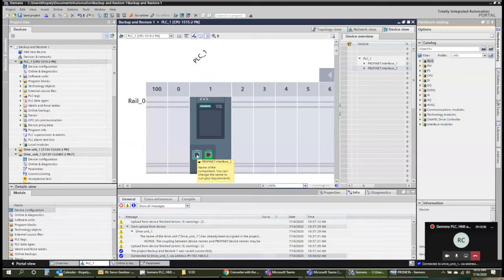What it's typically intended for is plant level communications, to talk to a SCADA system, or do some data backup to a higher level operating level. So while it can function as a machine level network, it's not as powerful as one. We also do sell separate communication cards that are Ethernet and not Profinet. But right, Corey? Yes, that's correct.